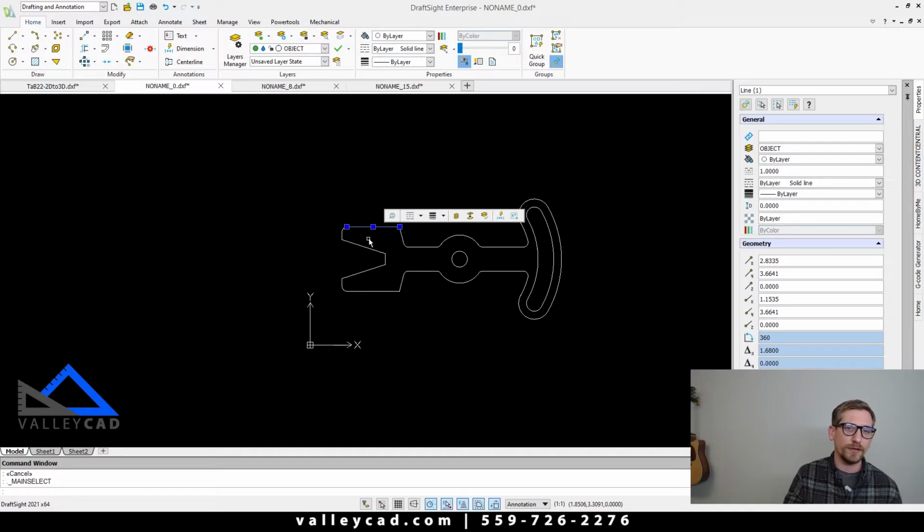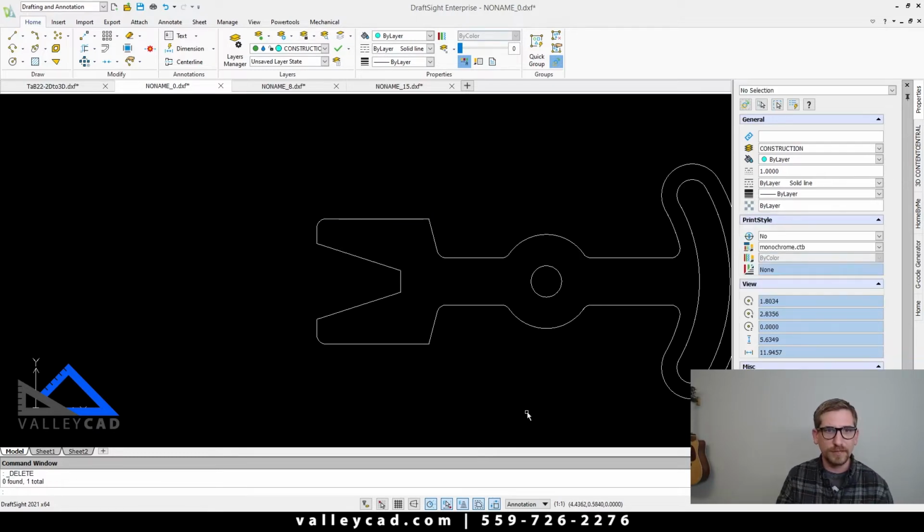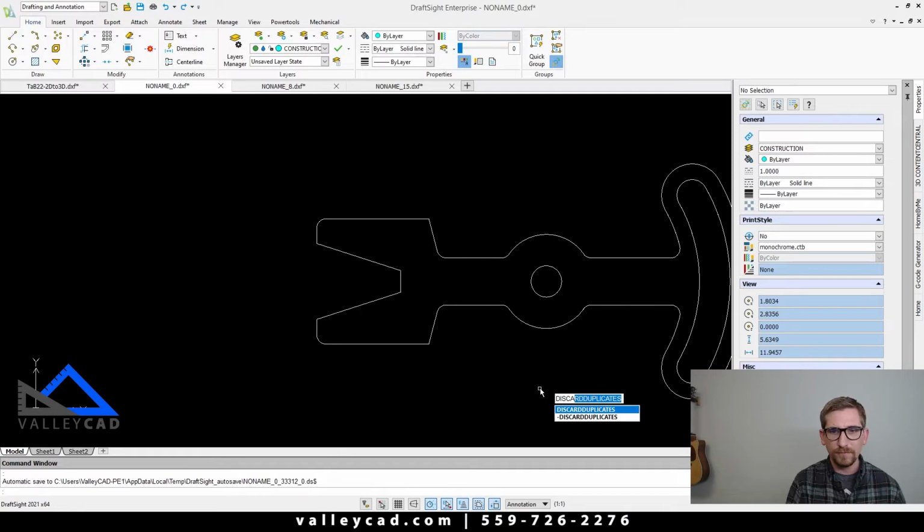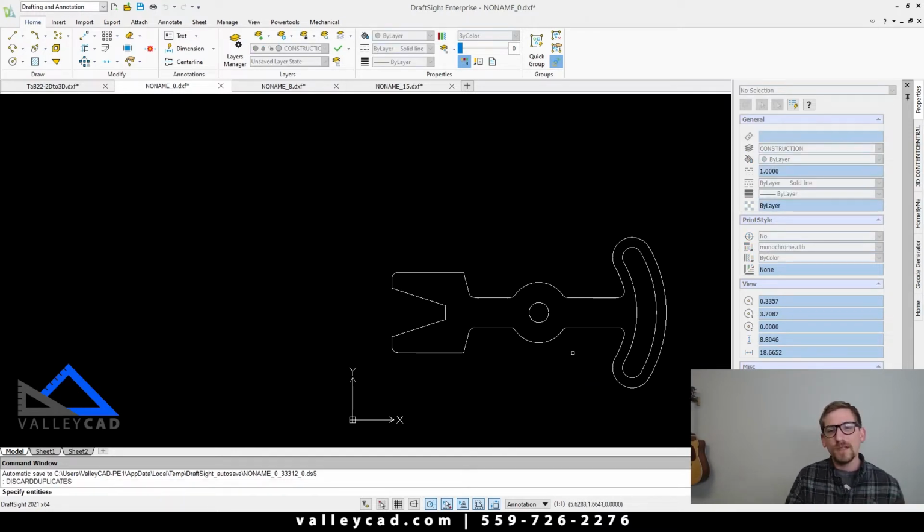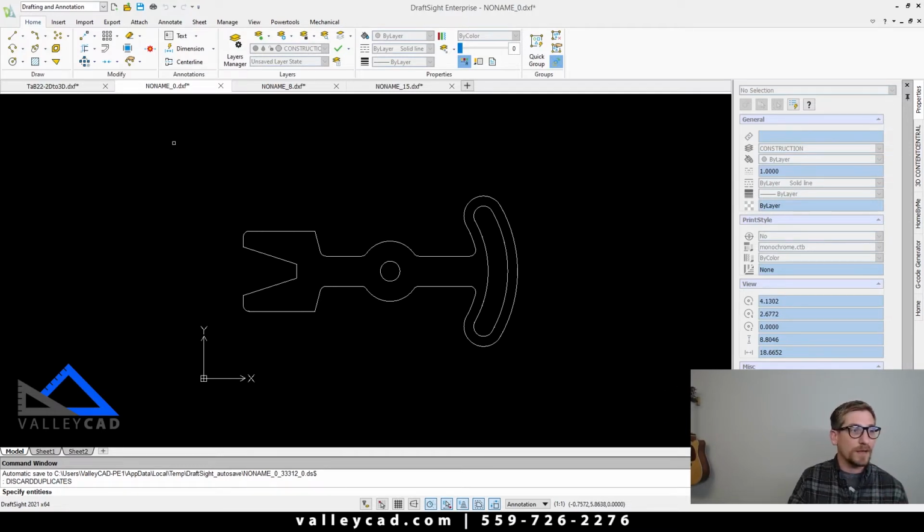So let's just verify though. If I click on this line and push delete, oh yeah, you'll see here that it actually did have an entity on top of another. So inside of DraftSight, there is a really cool tool here. And if I start typing in the word discard, you'll see here that DraftSight, you're gonna hear me mix that up probably a couple times in this video. But anyways, discard duplicates.